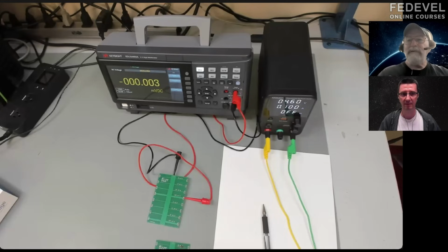And while we're talking about the application and the so what, I think the real value is when you're designing routing for power traces. Knowing what the resistance is of the trace, the path, and knowing how much current you can put in it safely before the self-heating blows it up. Knowing those numbers, I think, is really important to evaluate best design practices for the power path. And that's one of the things that we'll be looking at here as well.